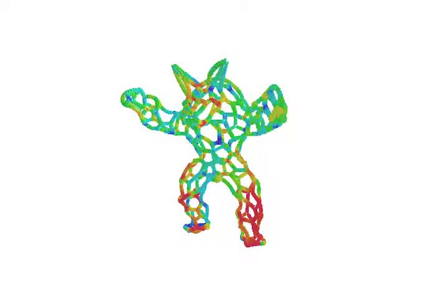To prepare the multi-material 3D printing, the armadillo rod structure is voxelized. Then, the Young's modulus of each voxel is mapped to a ratio of the two printing materials. Lastly, the material ratio is randomly dithered between the two printing materials.